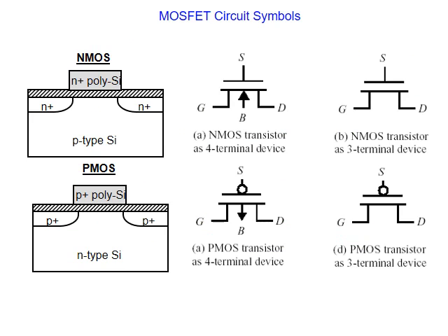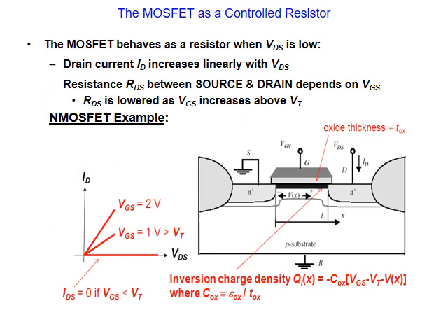As you can see here, this is NMOS when we have 3 terminals, B is there, and here NMOS when we have 4 terminals, here 3 terminals. The opposite here, you see the circle, just to mention that this is P type, and the same thing, either 4 or 3 terminals. Okay. Now still in the triode region, you can see here VDS against ID in the output characteristics. VGS was 1 volt. When it is increased and decreased, we can see that the resistance is reduced.